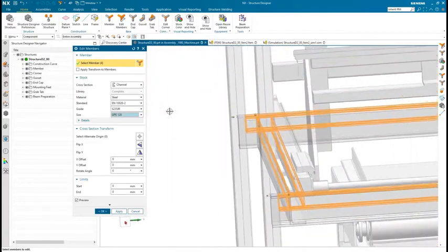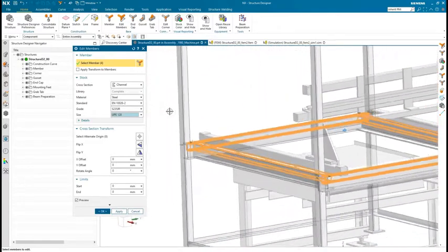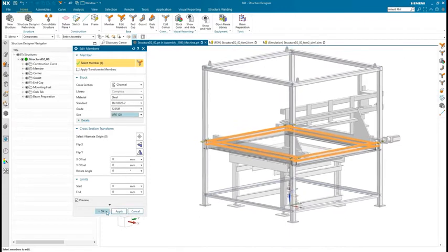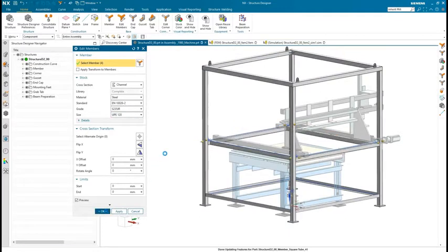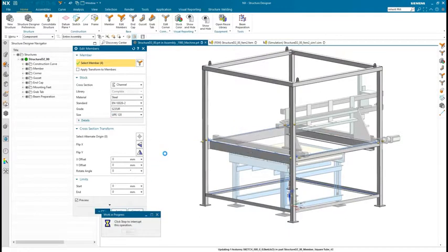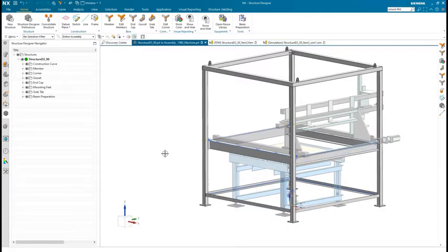We need to ensure the interior-most members can be welded to the flat side of the channel. During the swap, notice how we have full control over the orientation of the members. By visual inspection, the orientation is correct. Because of the rules, butt joints are added automatically.